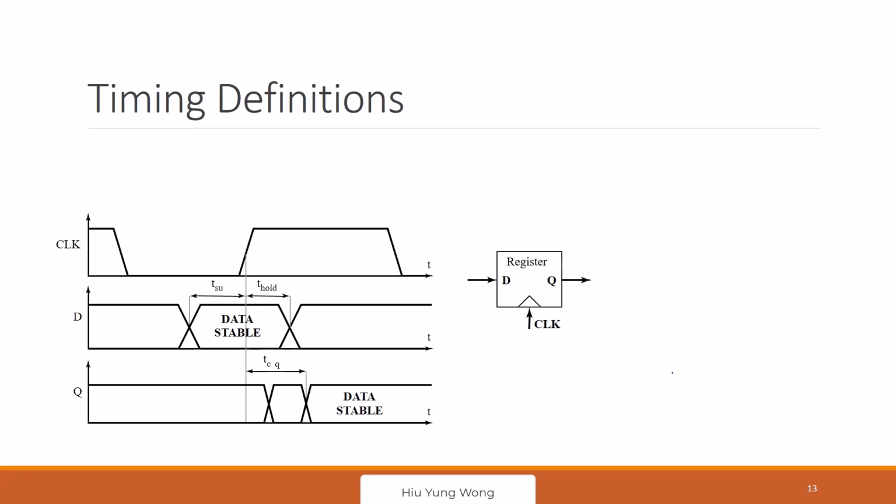So we say that it's going to copy for the edge trigger register, right? When the clock goes up, it should copy. Now we should realize that the clock is not going to be perfect. It has a slope, so we only look at the 50% point in time. To successfully copy a data, we need to meet a few things. TSU, which we call the setup time.